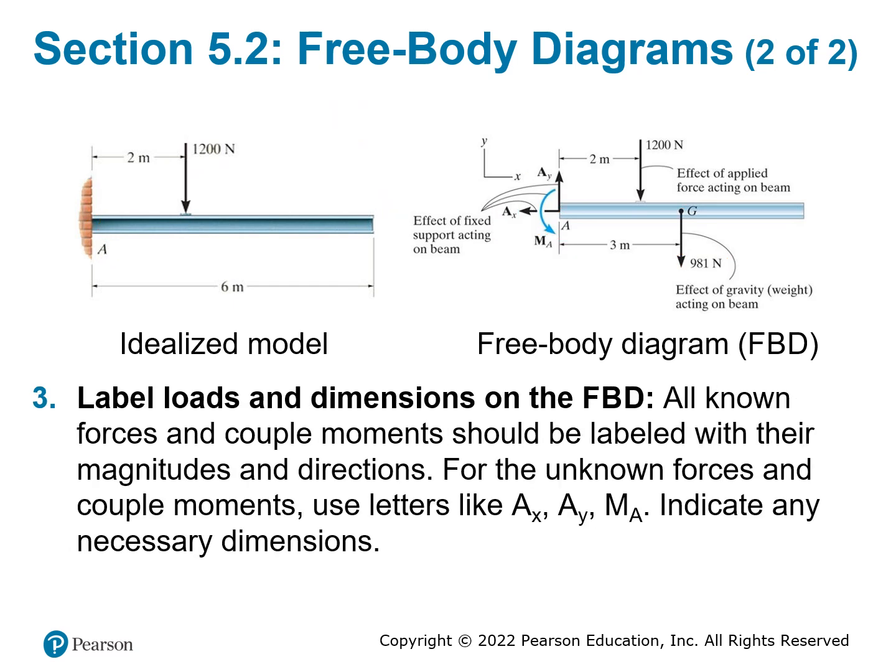So once you make the free body diagram correctly, we can start to label all the dimensions, such as the distance away from the reference point, because we need these to calculate the moment. And we mark any of the forces that we need to solve. So in this problem, we have 3 unknowns, AX, AY, and MA. And we already showed you that AX is going to be equal to 0 because there's no extra force acting in that direction.